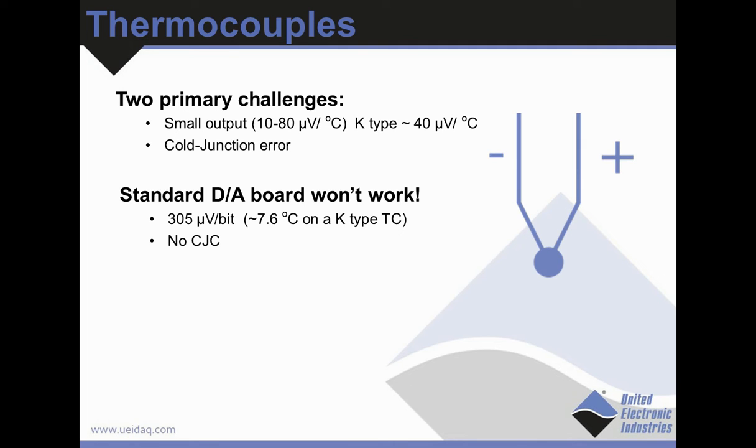That makes it 305 microvolts per bit, which is about 7.6 degrees C on a K-type thermocouple, and that's not enough resolution to do a good job in a SIL or a SIM.